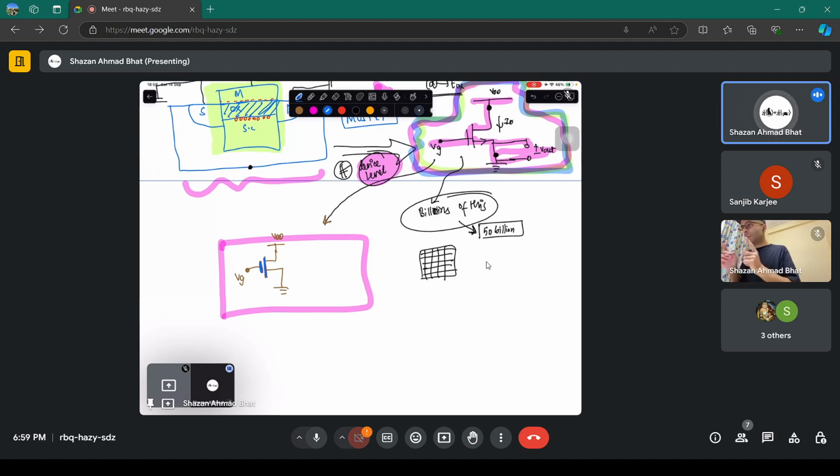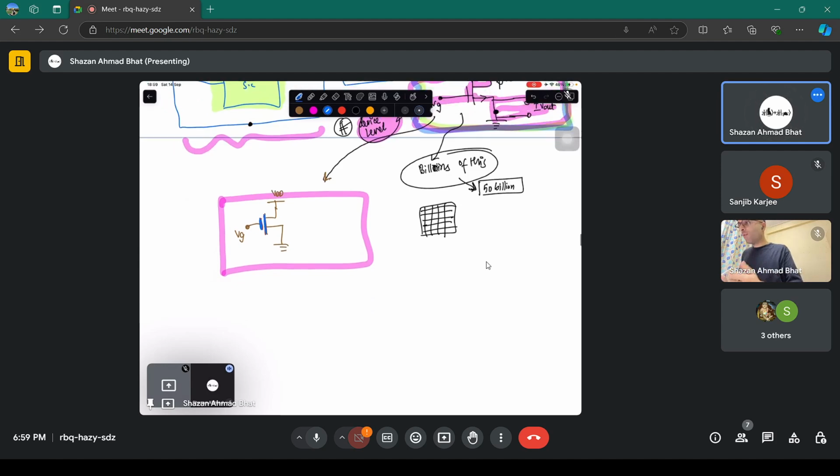It shows that this is a field effect transistor. What it means is that whatever field you are applying is inducing certain things here because of the electric field, not because of direct coupling. It's an indirect coupling because of the electrostatic field generated by the charges. The charge does not flow in this direction, ideally, because there's an oxide present here. So that is the actual representation of this particular schematic.